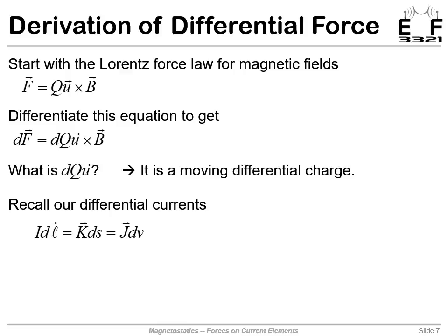So that takes us back to the differential currents that we discussed. We talk about the Biot-Savart law, one for line currents, one for surface currents, and one for volume currents. Let's look a little bit more deeply in the volume current term. So current is simply charge moving at some velocity. So J equals rho times U. Now we can swap U and dV to have rho dV inside of the parentheses, multiplying U.